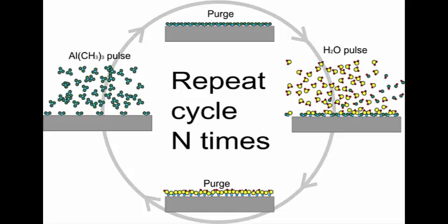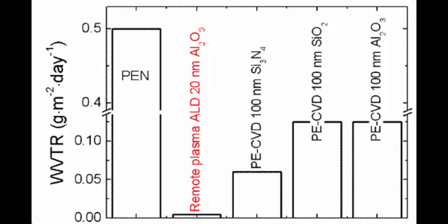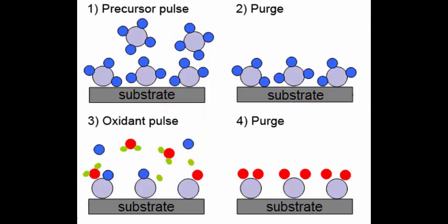Some advantages of self-limiting film include uniform surfaces, high conformity, high control and accuracy of atomic level thickness, etc. ALD does have some limitations including slow rate of reaction, etc. Research is still being conducted to more completely understand the process of ALD and how to improve it. ALD is similar to other common deposition techniques such as chemical vapor deposition and molecular beam epitaxy.